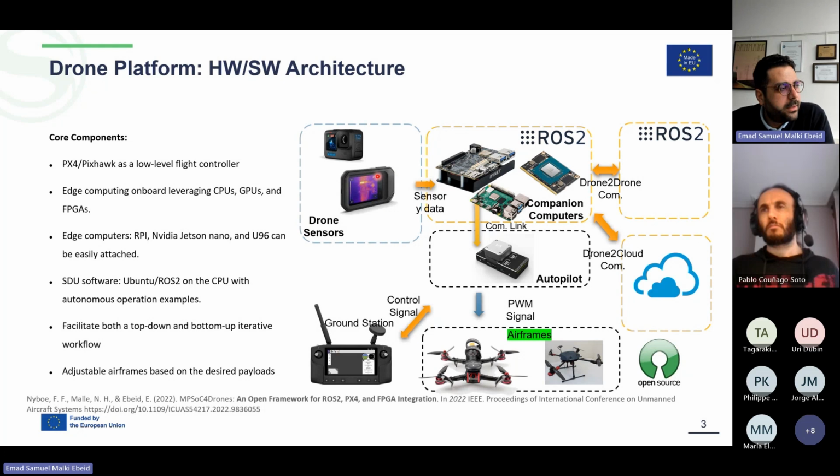Sensors-wise, the drone will have its own small RGB camera connected with the Raspberry Pi. Yeah, and it depends on the case. One maybe needs a stereo camera to estimate the distance and so on. So that we need to discuss, how heavy is the camera and so on. But for now, the drone can carry a small stereo camera, like Intel RealSense, and then the camera somehow has to be a part of the algorithm, maybe for the swarm. Then a lot of work coming in the CPU side.